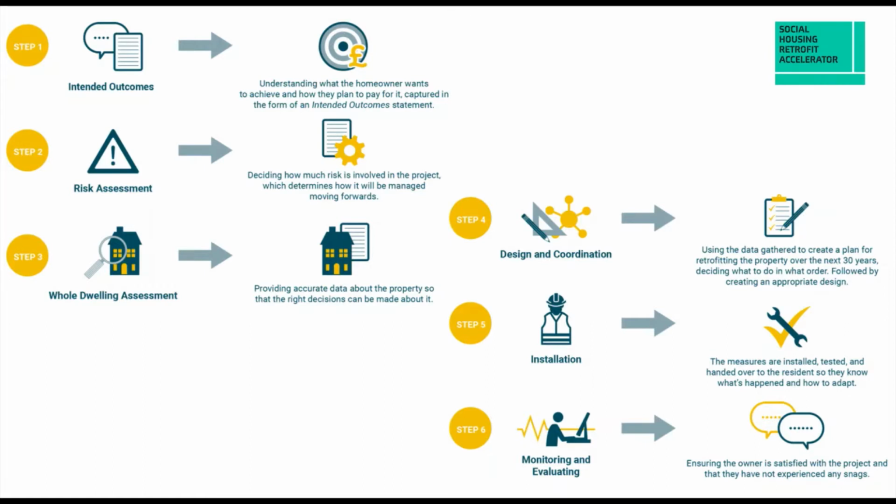And this looks at a holistic view of the property. So for example, if we're switching over to heat pumps, ideally we do want to be looking at what the pipe size is, what the pipe runs are that are going out to the radiators. Can those radiators be retained? If we put more insulation in, will that adequately mean that the radiators are adequately sized to switch from a high temperature boiler to a low temperature heat pump? We need to look at that in quite a lot of detail to be able to scope out a retrofit and make sure that it's suitable.